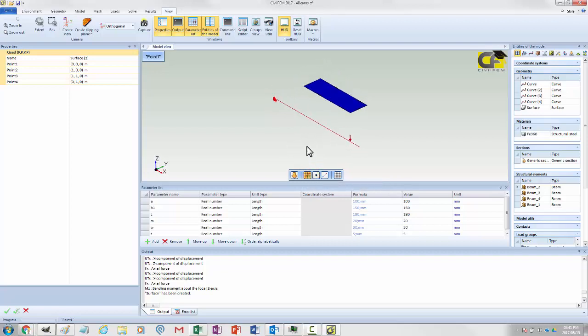So now we can see there's our beam section that we've created initially, which should have the same length as this one over here. Right, so for the second surface, we can now also use our parameters, which is useful in this case so that we keep our system parametric should any of these values change, so that our locations will update as well.